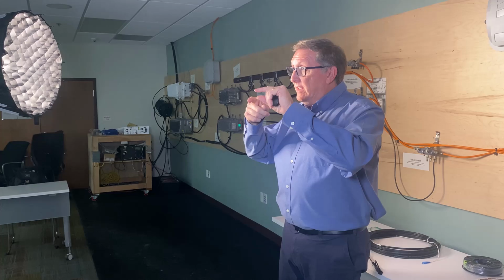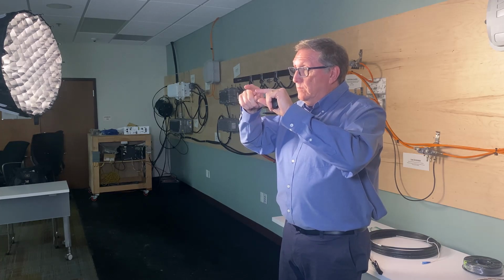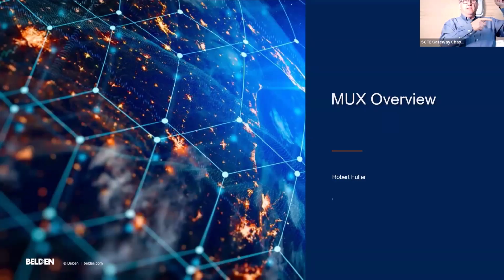There was a guy putting in an E-clip. The drill caught, the clip bent to the side, and he just straightened it out. Most of the drops have fiber protection, and it might not cause an issue, but it might. That's one of those little bends where you can cause damage. It might not be an issue right now, but down the road, it's one of those install quality things. So pay attention, take your time. Fiber is rugged, but it still needs to be taken care of. Okay. Any last comments before we roll to the next section? Excellent. Thank you.